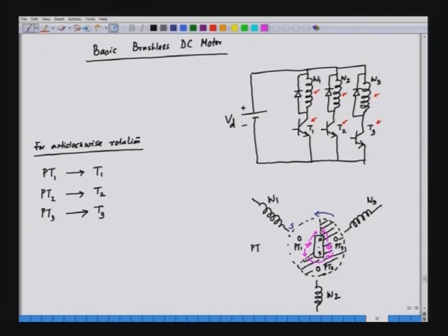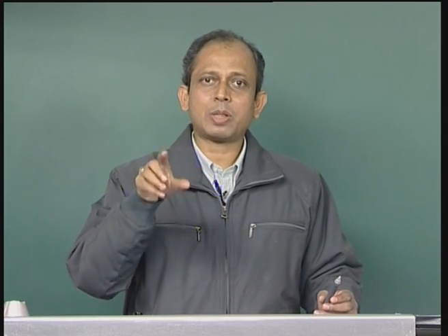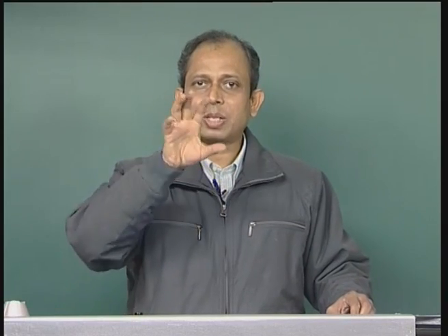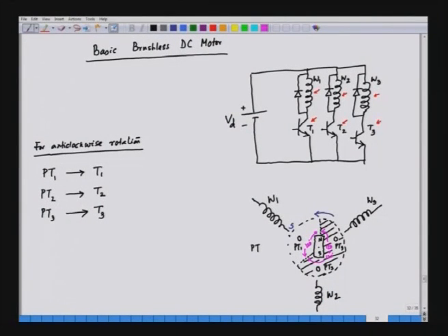So, this disc will be pressed onto the rotor. It is glued on the magnet. The rotor is basically a magnet having a south pole and a north pole. So, we make this disc which has a 240 opaque region and a 120 transparent region, and we glue this to the rotor so that it also rotates along with the rotor. As the rotor rotates, the disc also rotates.